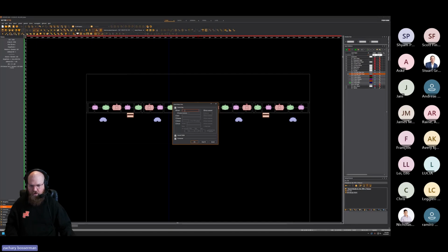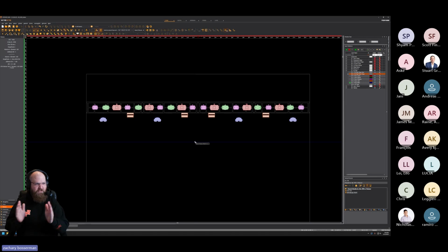We're going to hit Q, select our patch. We're going to start with 1.1, which is the patch that we were given. And the way this patch is laid out, this patch is kind of working one half of each truss as a universe, and then all the things around the front are a different universe. This is pretty common because we have all these fixtures here lined up together. They're going to go 1 to 1 to 1 to 1 with short DMX cables. Then you're going to have a second universe that's going to start over here, and it's going to have these short DMX cables across the way.